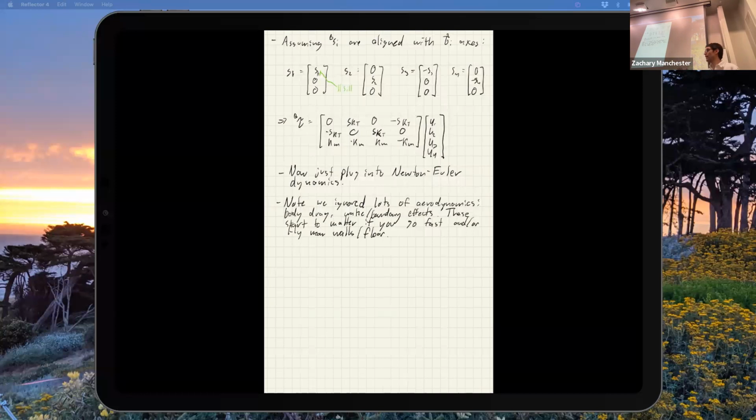There's a few labs that have done a lot of work on doing residual learning, basically, to learn these extra dynamics terms from experimental data to try to do better prediction. Davide Scaramuzza's lab in Switzerland has done a ton of work on this in the last few years, and they've got really ridiculously impressive models now that they've collected tons of data sets in a big mocap arena. They can do insane aerobatics and track to a few millimeters worth of accuracy over tens of meters at insanely full-gas speeds, which is awesome.